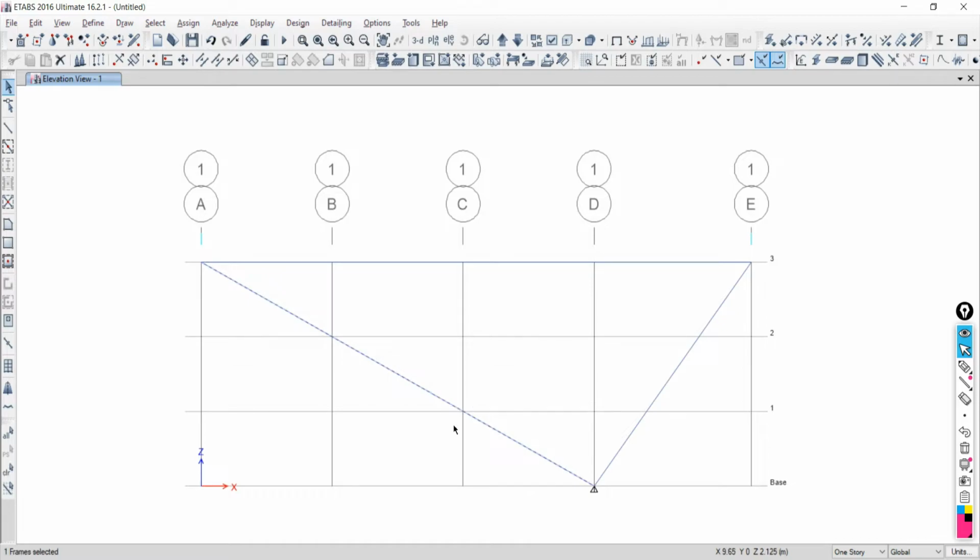Right? Yes, sir. But the problem is what, we actually have to divide all these frames at these joints. So okay, let it be, later on we will talk about how you can divide it. So go to frame, close this, from this point to this, click over that, right click to off this continuity. Now from this joint to this, click over that, right click.